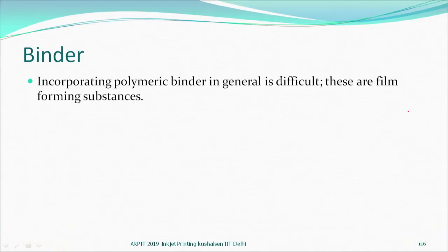The binders, as we say, are required, because they are the film forming substances and they are going to be part of the ink. As we said, they should have a low Tg, so that after the binding has been done, the fabric in the design area is also flexible, because we do not want to change the flexibility.